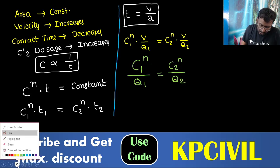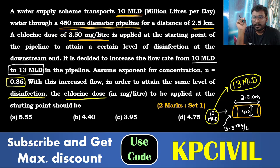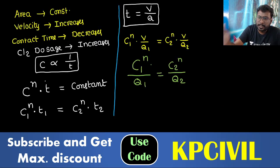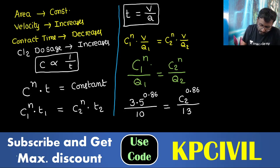So you have all except C2. C1 provided is 3.5. n is given as 0.86. Substitute in it: 3.5 to the power 0.86, Q1 is 10 MLD, C2 to the power 0.86, Q2 is 13 MLD. Now solve for C2.